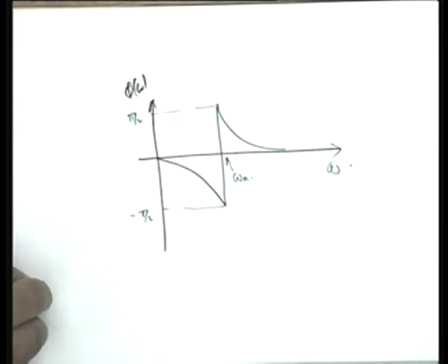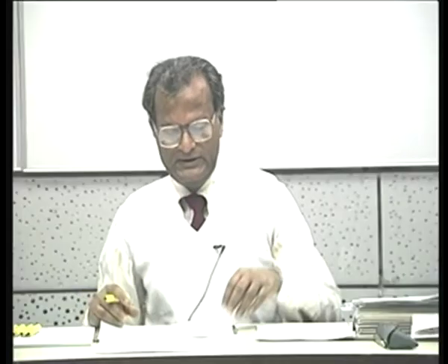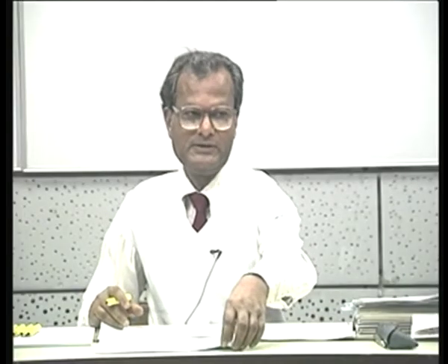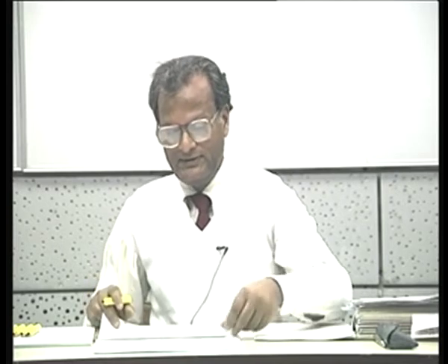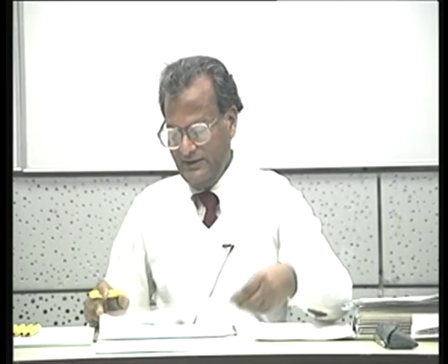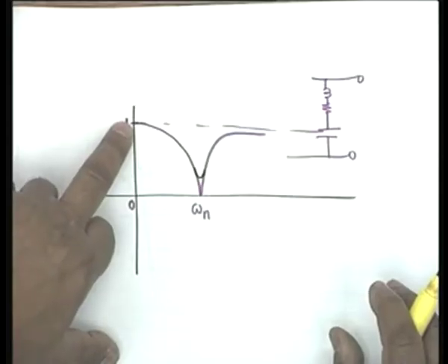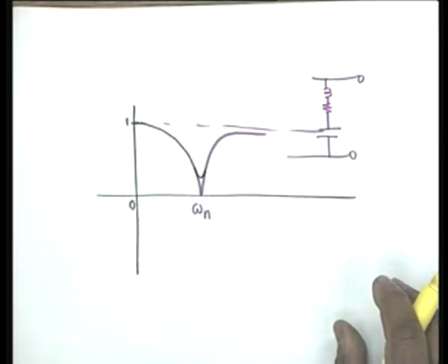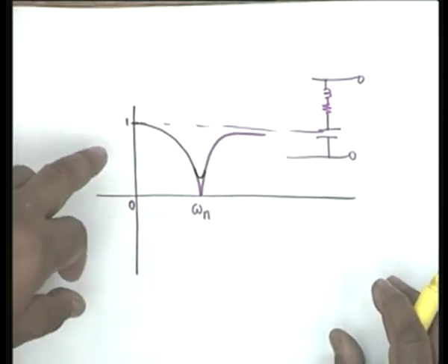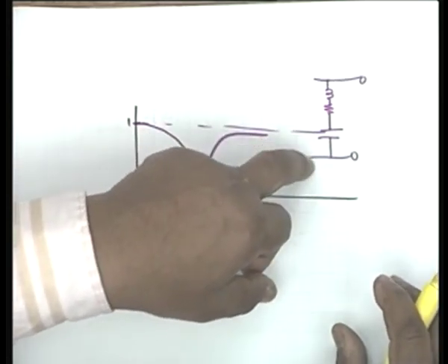Next, third part, very few people have attempted, and I thought that would be very simple. This concerns the half power frequencies. If you look at the magnitude plot, obviously maximum power is at DC or at infinite frequency, the maximum value of the magnitude function. Half power would therefore mean the frequencies at which the magnitude becomes 1 by root 2.